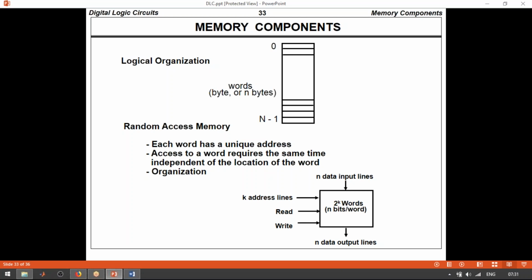Programmable read-only memory. In the case of electrically erasable read-only memory, through electric pulses we are removing the content inside the memory element. And in EPROM, you have a portion to erase the content which is closed with a glass packaging. So through UV rays, if you pass them through that glass, it will automatically erase the content.